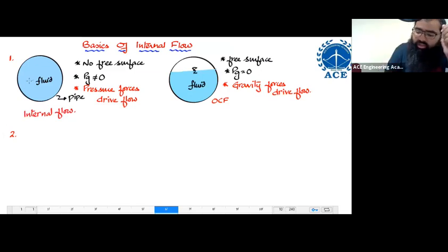Throughout this chapter, throughout this internal flow, we are going to discuss real fluids. Real fluids are flowing over here. If real fluids are flowing, then viscous forces are going to contribute in the flow. If viscous forces are contributing, we are looking at the relative effect of viscous forces on the flow. And that relative effect of viscous forces is given by Reynolds number. If you're not following, be patient. Everything will fall into place if you are patient. The concept now is Reynolds number.